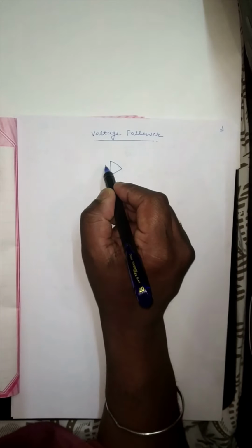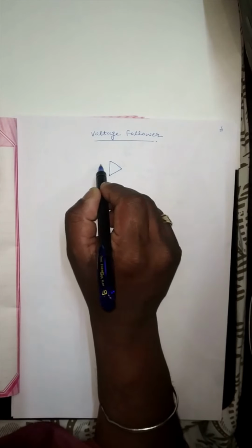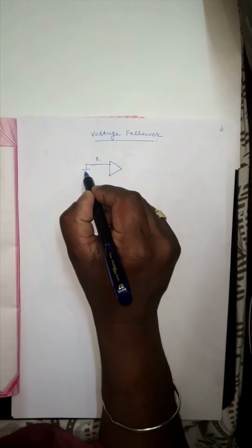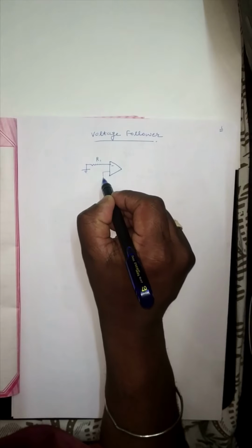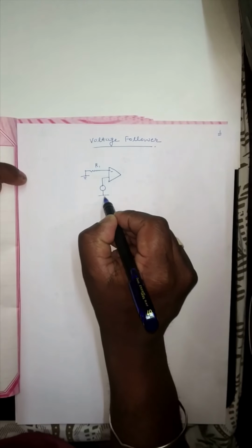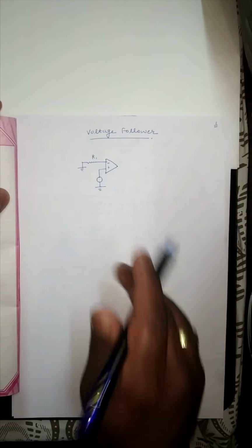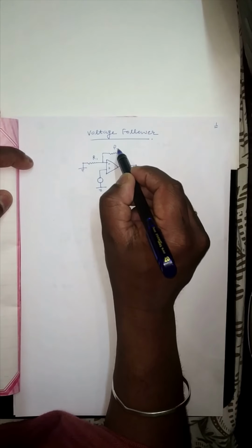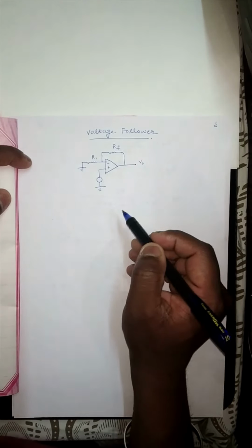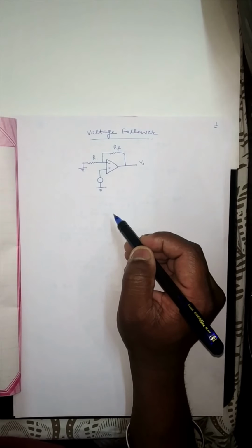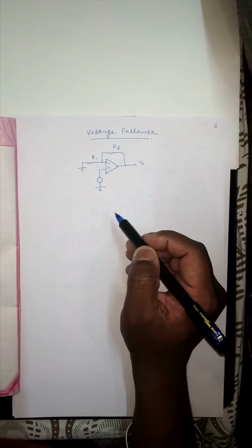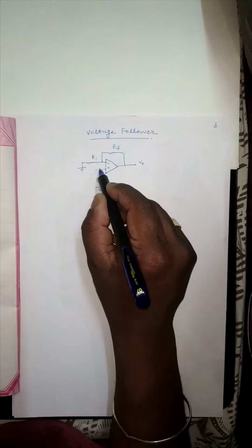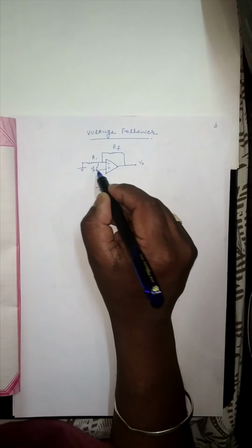So now we take the example of non-inverting amplifier. So we are having the inverting terminal grounded and we are applying the input at the non-inverting terminal. So we are having a feedback resistance, that is RF. So this is the diagram for the closed loop non-inverting amplifier. Let the input given is Vi. So in this case, let the difference between the inverting and non-inverting voltage is Vt.